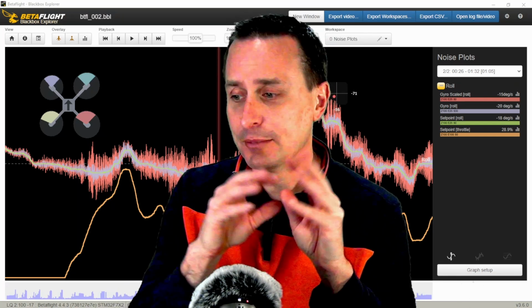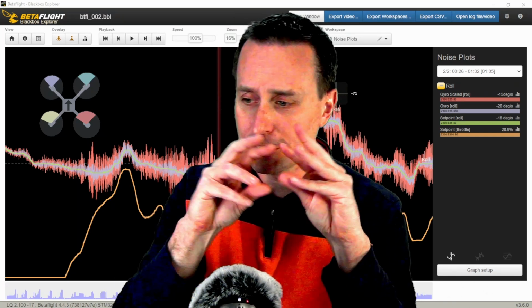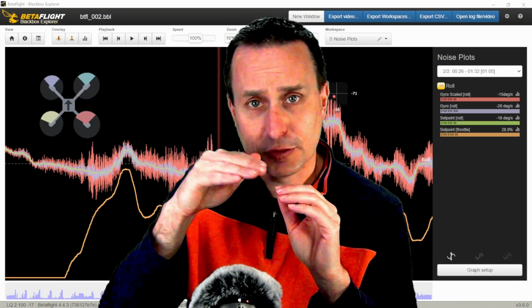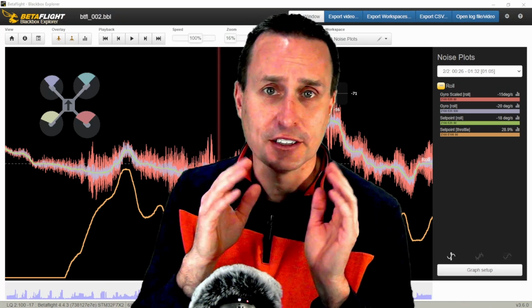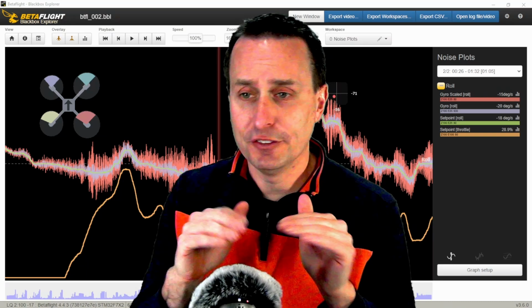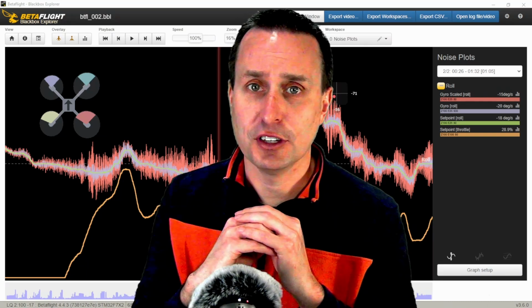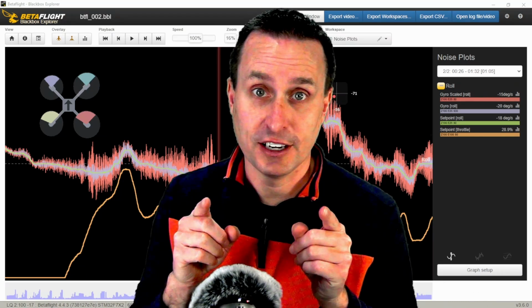I told them to check and make sure no wires are hitting the flight controller anywhere, or that a wire isn't just touching the gyro somewhere where it can cause issues. He did that, and it solved it. Check for that kind of stuff as well, of course. Let's move on to the next one.